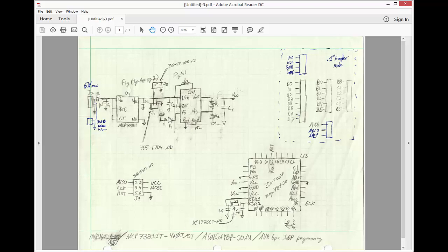In terms of what it was going to run, I went around and around on this. I considered an ARM processor. The TechBots library, which I'm going to show you, does have an ARM processor in it. It's plenty powerful, has a lot of features and functions, and there are actually some really good libraries for using it. But at the end of the day, I decided to go with something that I knew most people would have more experience with rather than something that was a little more cutting edge. Which was decided to go with an Atmel processor, specifically a Mega 48, just a 32-pin version of it.